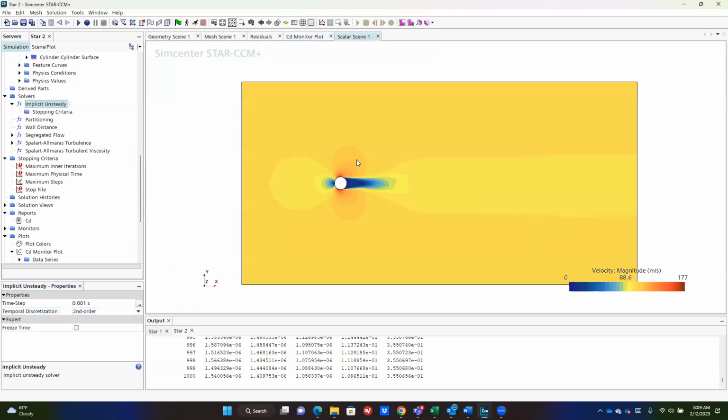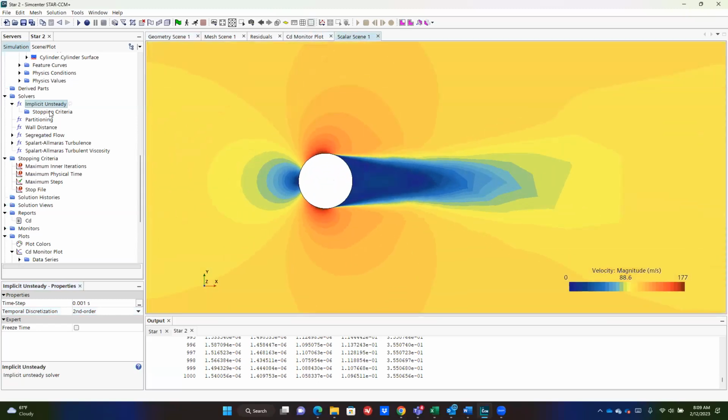My approach to identifying a time step size, I just default to 0.01. My approach to this is you find how long it will take a fluid particle moving out here to reach the trailing edge. This is called a convective time, which is the length over the V infinity.